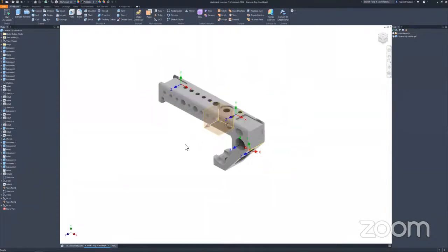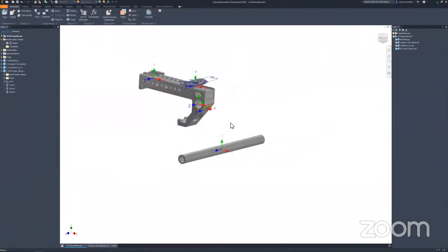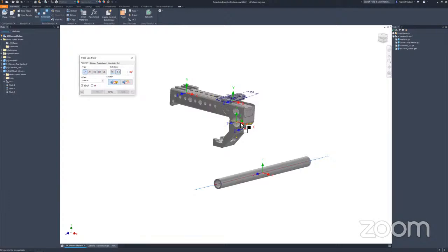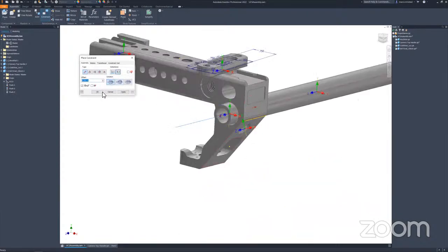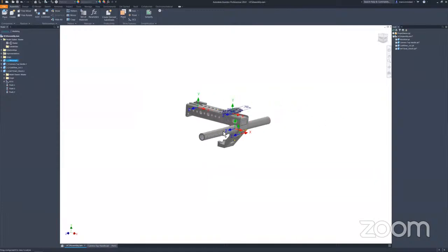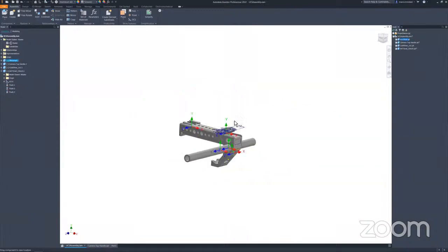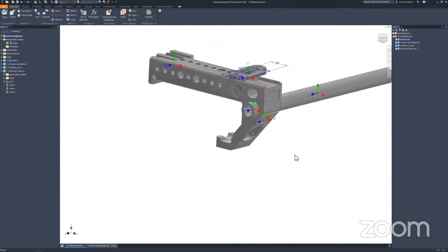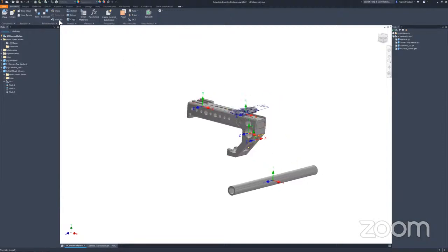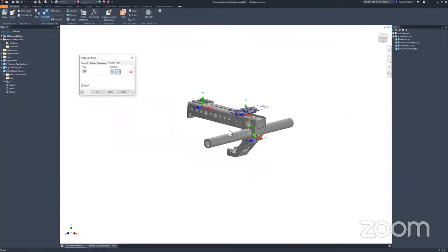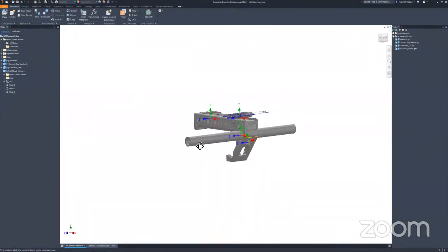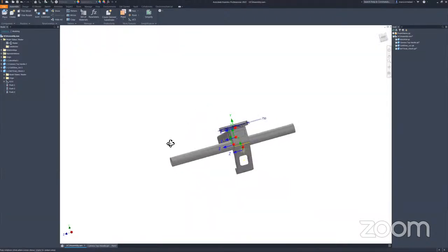Yeah. And so what I kind of noticed back in here is when I used a normal constraint between this and this axis on this one, if I go ahead and place that, you can see that it's kind of still moving in quite a few directions. Yeah, absolutely. If you guys are familiar, when you place a part in assemblies, you could right click and click grounded at origin, a common option that people start assemblies with. That'll effectively fix the origin of that part to the origin of the assembly. Right. And that's a good way to kind of coordinate parts.